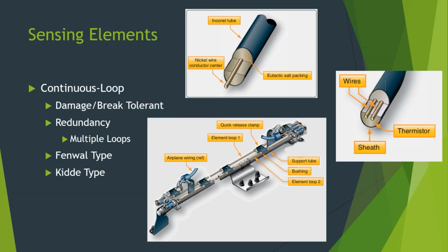Well, they're normally both in operation, and you can use one or the other as the backup. Why do we have that backup? Why would we do it that way? We say, okay, we're going to give up some of that check and balance. We're going to make it more prone to having a false alarm. Why are we okay with that? What's that going to allow the airplane to do? What's that going to allow our operation to do? It's going to allow us to keep flying until we can get that plane into a location where maintenance can be performed. Okay, it's called a deferral, a deferred maintenance action.